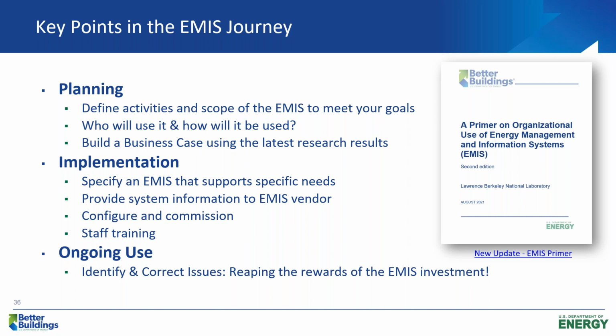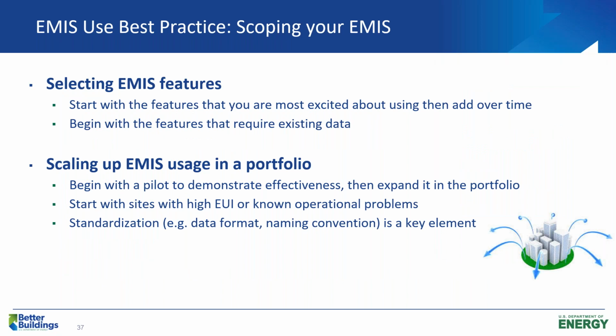All right, next slide. I'm going to talk about just a couple of best practices to round out this presentation that we've seen a lot from our campaign participants and just over the years working with owners. One of the key things is selecting an EMIS with features that you want to use. So don't select an FDD because it's what your neighbor's doing. Select an FDD because you really want to see what faults are going to show up for your systems. You want to close the loop on those faults and make it a part of what your business practices are.